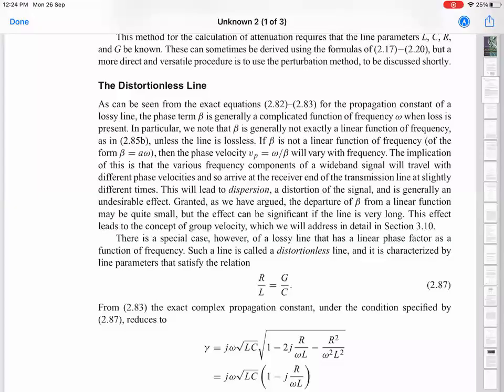So depending on how narrow band or broadband your signal is, going back to one of our discussions about these transients, when you turn something on, even if you turn on a pure frequency, the very fact that it turns on at some point means that it has a finite bandwidth of signals. So if you are propagating very, very short pulses of, say, a signal at 5 gigahertz, but the width of that pulse is only a nanosecond or so, then that represents a very broadband signal in frequency space. And the bandwidth will be roughly inversely proportional to the width of this pulse.